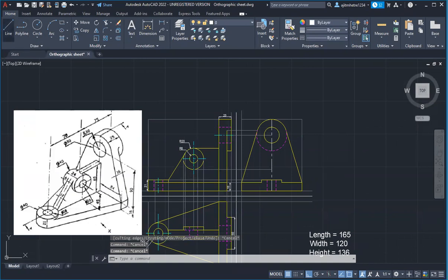So when you are seeing from here, that means what? 24 will be divided from the line part. So 12 left, 12 right. But the height of the rectangle, see, a rectangle will be made ultimately, but in the case of a side view, the 24 will become the length and the height will become 40. So in this case, from here, I'll come this side, and type 12, enter. Above I'll go, that is 40, enter. And then once again, I'll type 12, enter. This is my final box, which is a part.